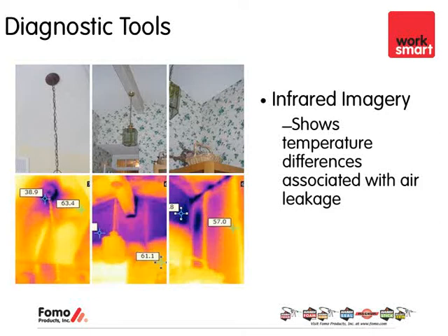Then the third picture is showing a great example where you have adjoining building materials, and those adjoining building materials have not been properly sealed. And again, you can see by the black or dark purple, that's much colder conditions. So as this house is being depressurized, it's actually pulling that cold air through the adjoining building materials. Again, it'd be a great area to address for air sealing.